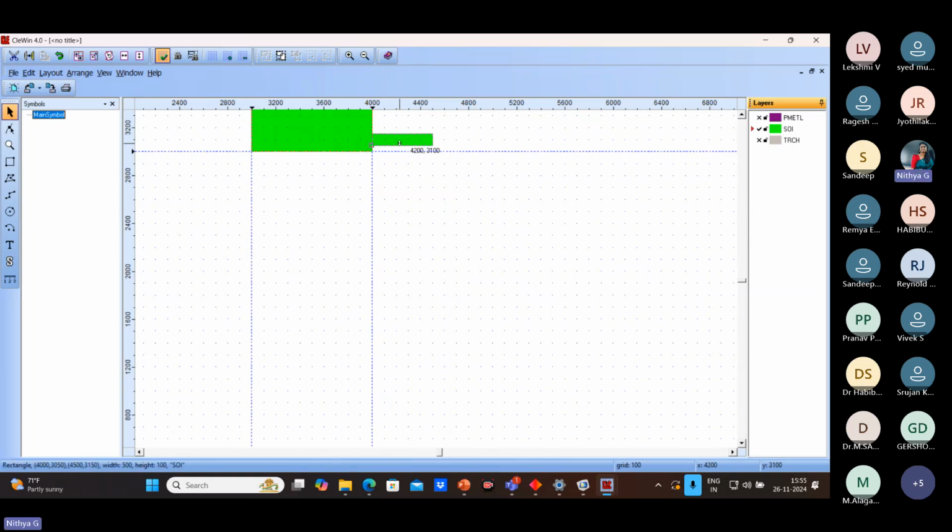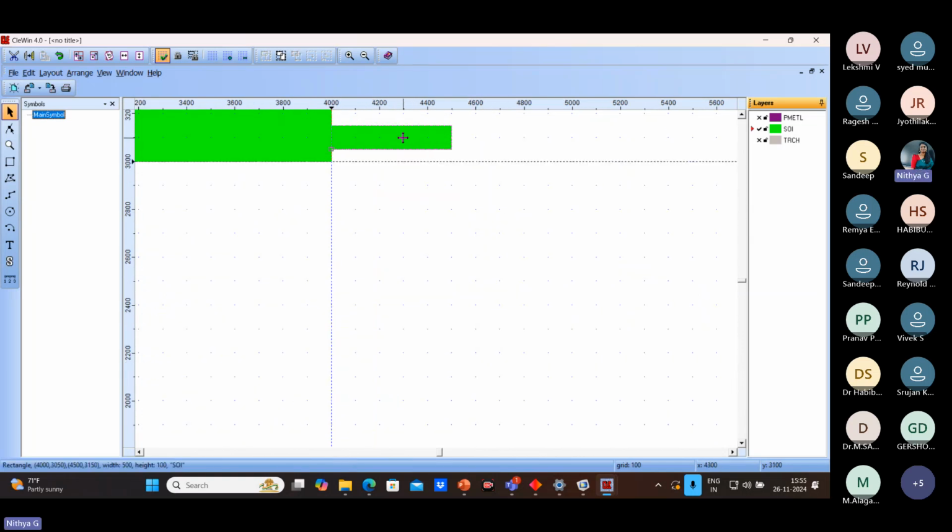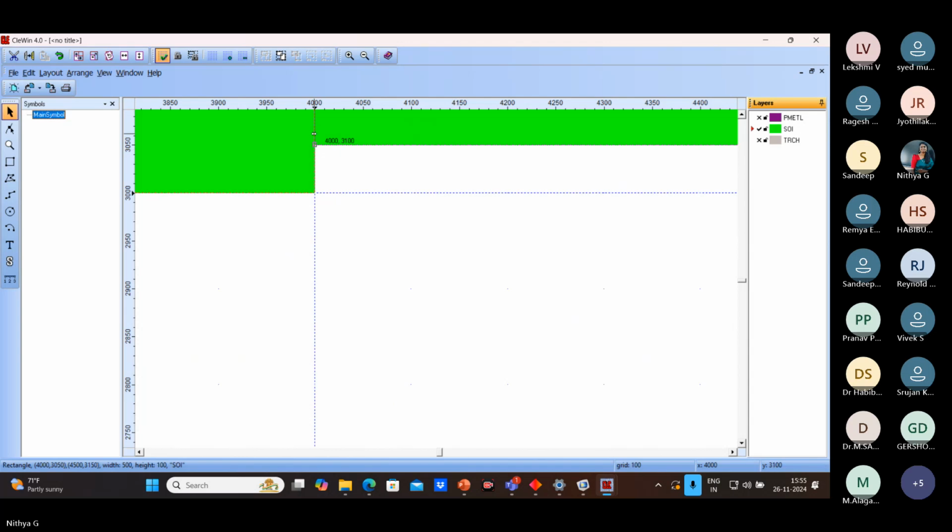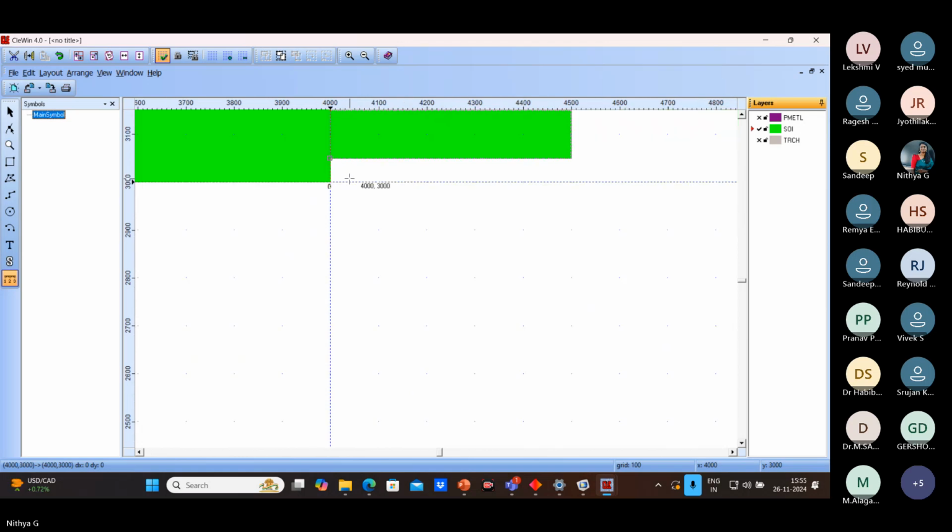Okay. This is how you need to have a gap, is what I was saying. Don't connect exactly at this, because during the trench etch there is a high chance that some of the SOI area may get deleted, or I mean etched. So it is better to keep a certain gap.